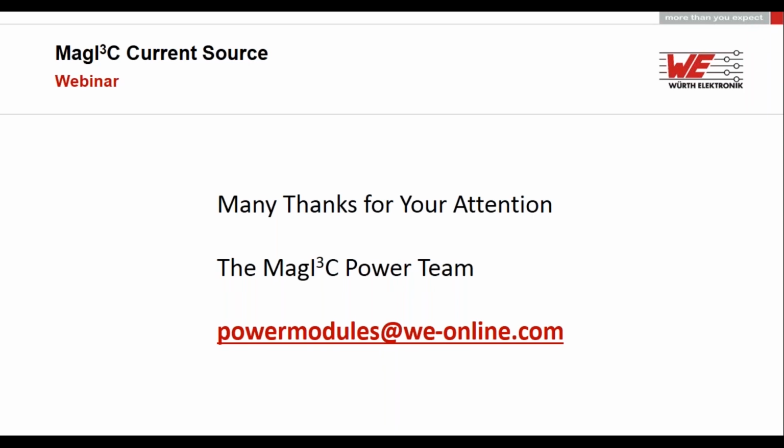So there's also another question. Why a PI regulator and not only a P regulator? You really need a PI regulator if you compensate the buck regulator itself. But then you have a really fast regulation. And if you only use a P regulator, you will not end up in exactly the current you want to have. You need an integral part if you want to have the actual current exactly like the set current, the set value of the current.